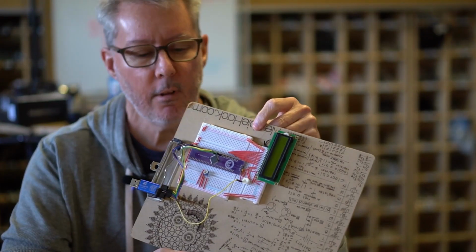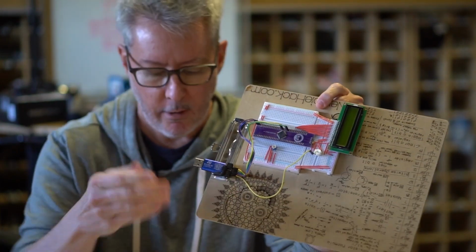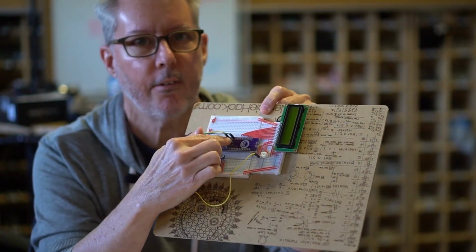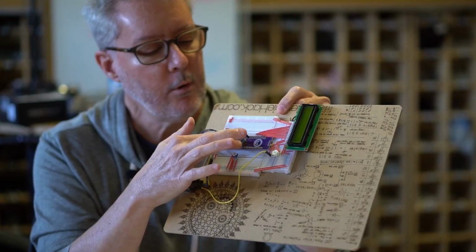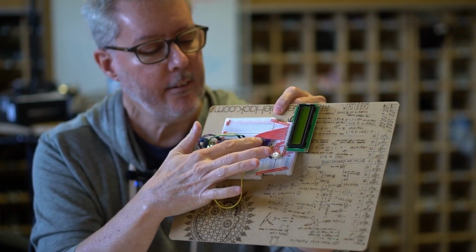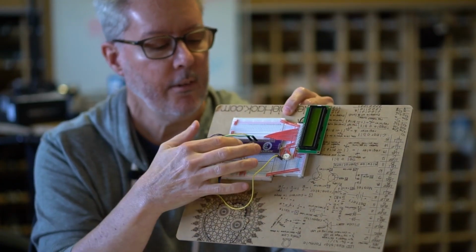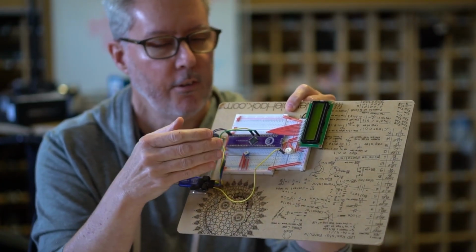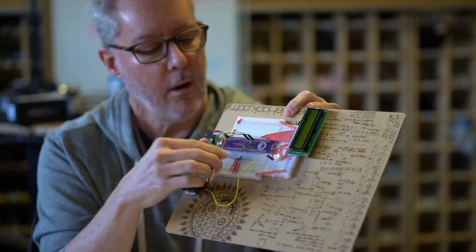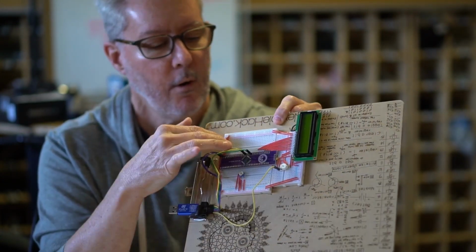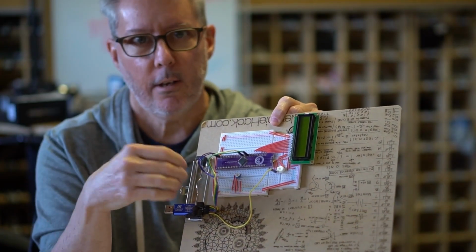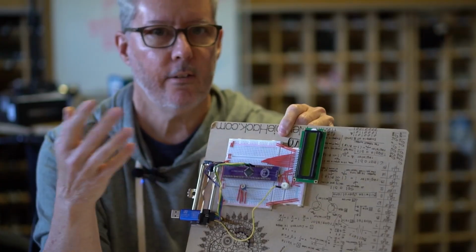This is an example of how you use the microcontroller. So you have the microcontroller like this that is in the middle of this circuit board here. The circuit board is only the microcontroller, and it's broken out into these pins. That's it. There's no other components on this circuit board, so you know that you're designing specifically for this chip. And then when you go to create your product, all of the components you add around the microcontroller, you can easily design in your PCB designing software when you decide to put out a product.